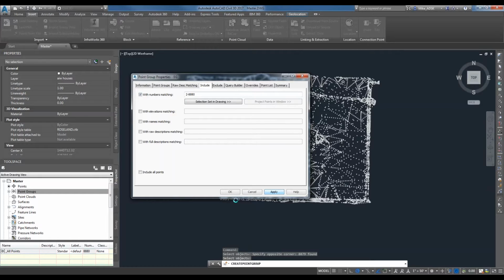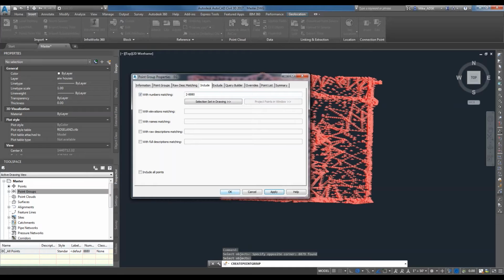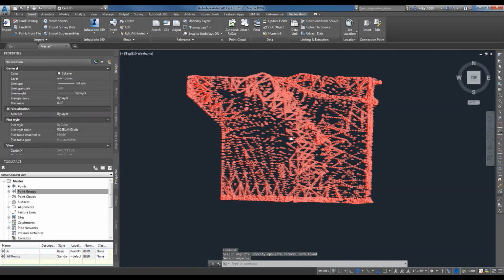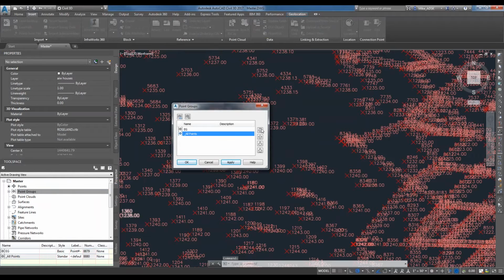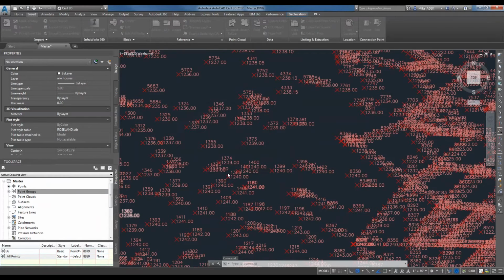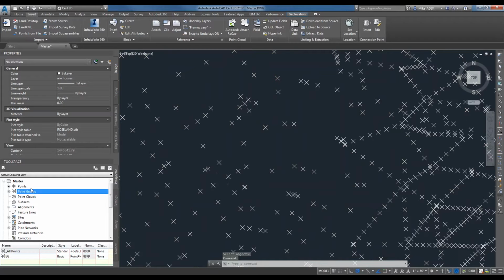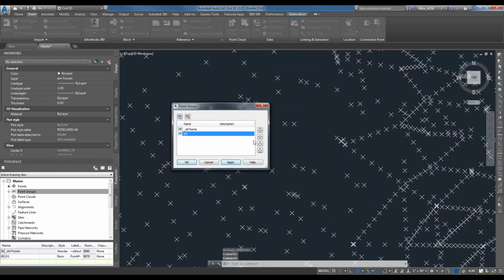So now we have, crank through it over here. And notice that it changed the way that it looked. Now why? We're actually going to touch on this a little bit later, and in AutoCAD you also have a little bit of this, or actually this is a pretty prominent feature in AutoCAD as well, but styles. So the styles that I used for existing grade, I just used some basic styles. If I were to go to point group and bring this back up, it would change back to how they looked before. So for now, I keep those points up there.